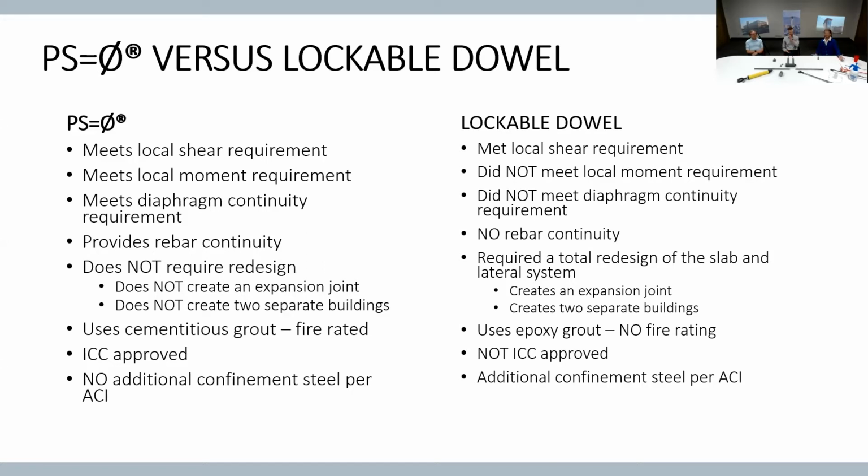And we use a cementitious grout, and not epoxies. Epoxies have actually been banned. Epoxy anchors have been banned in a couple cities around the country just due to pullout. It creates a sudden brittle failure; it's a pullout. And ours is ICC approved.